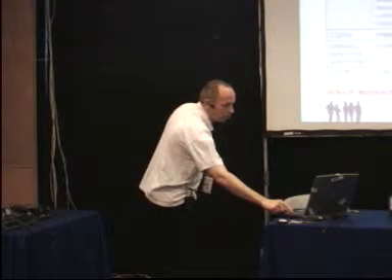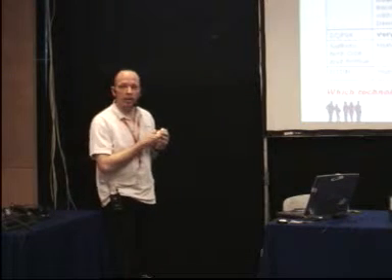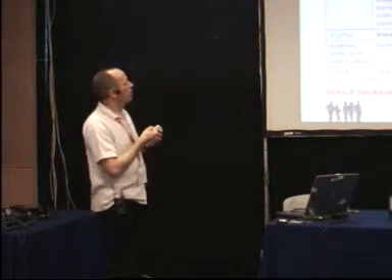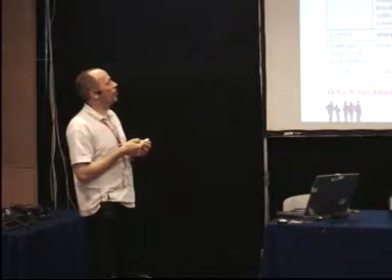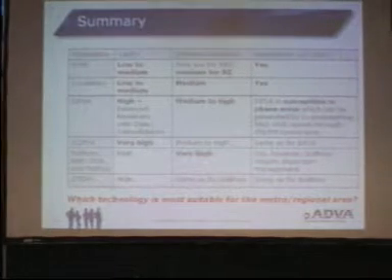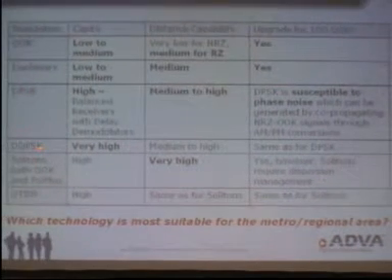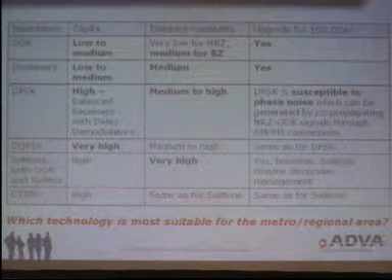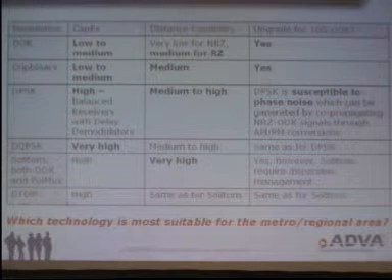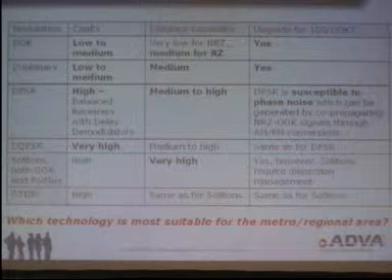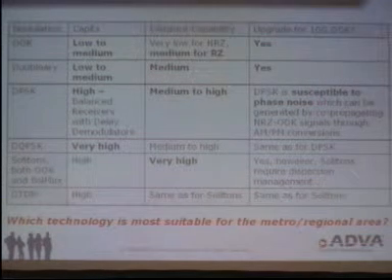So, nice contender, but it doesn't work as an upgrade technology. Pretty much the same with DQPSK. Hence we have a matrix, a summary. On-off keying, including, by the way, carrier suppressed return to zero. This is still on-off keying. Low to medium effort. Pretty good distance capabilities, and yes, it is a candidate for upgrades for 10 gig on-off keying. Pretty much the same for duo binary. Completely different with DPSK and DQPSK. They can have very high distance capabilities, and in effect it's these which are discussed for multi-thousands kilometers transmission systems, but then it's green field installations. No on-off keying on adjacent channels. So they can't be used, as I said. And there are some others which I didn't even mention.